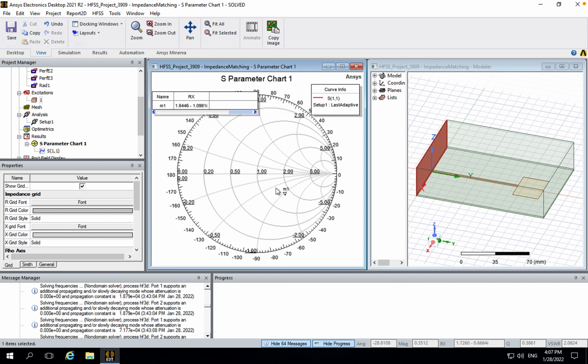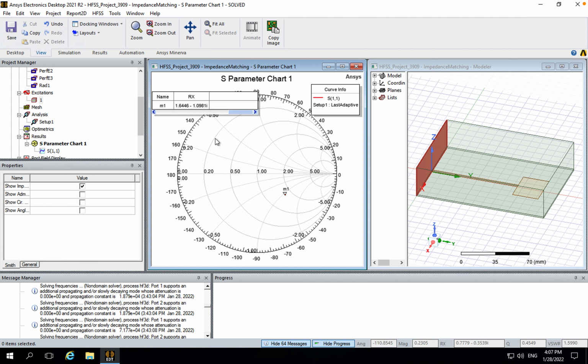All right, so we are on the Smith chart. We are at point 1.64 minus 1.09 J. So from this point, and knowing that we renormalize to 50 ohms, you can multiply by 50 ohms, and then you can find what the input impedance at this reference plane is. But now the question is, how do we find the load impedance? So what you can do is, of course, knowing the length of the line, you can go back to the load, so you can rotate on the Smith chart and find what the load impedance is. But on HFSS, it's actually quite simple.